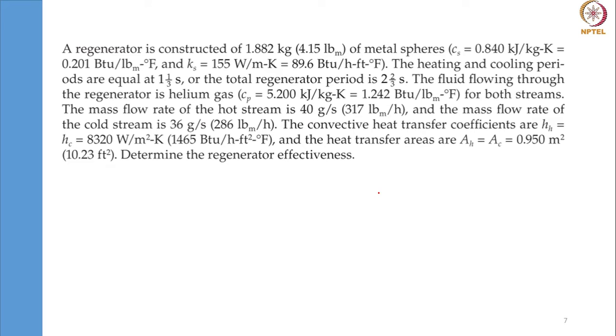So the next step for us is to find the NTU of this heat exchanger. That is defined as UA by m dot Cp min.